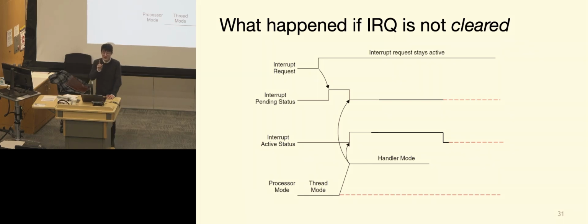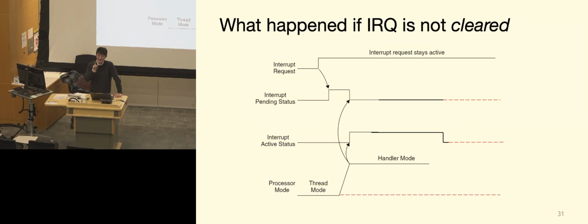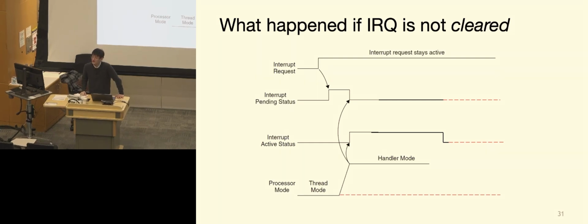However, the answer might not be just like that, because there's something else also checking that. Any other thoughts? So the interrupt active goes low, but it immediately gets interrupted again. And does that cause any changes in other signals, for example the pending or the active?